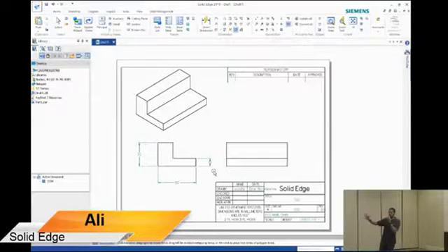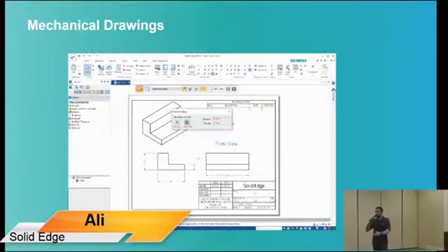And it's very simple to make a Quick Sheet. You just go to the commands. In terms here, I'm just saving it, basically. It's very safe. But then on the left side, you go to the application button and you find the Quick Sheet command available in the tools. Or in the settings, it's Create Quick Sheet right there, and it creates the template very easily for you. So if you have 100 parts for your solar cars that you want to make engineering drawings of, to send to your machine shop to machine for you, you can just use the Quick Sheet and streamline that whole process.